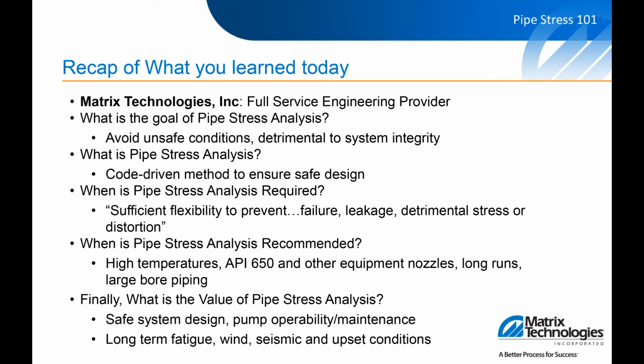That's kind of your key points. What's the value of pipe stress analysis? Safe system design, pump operability, any kind of rotating equipment really. Long-term fatigue, wind, seismic, upset conditions, just an overall safe and robust system.